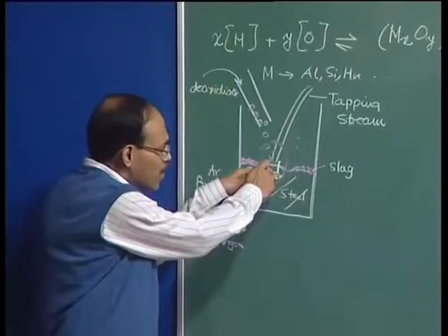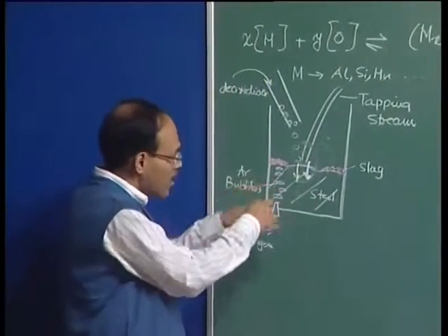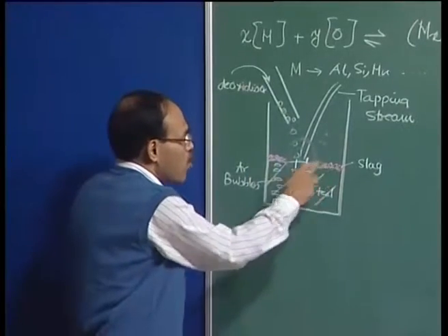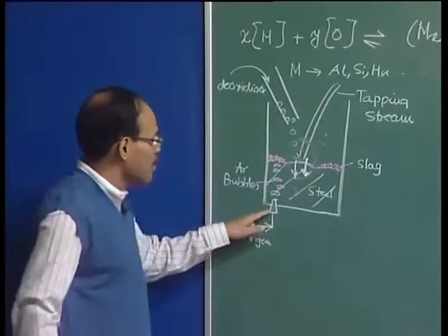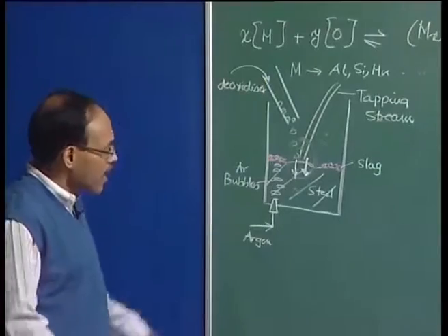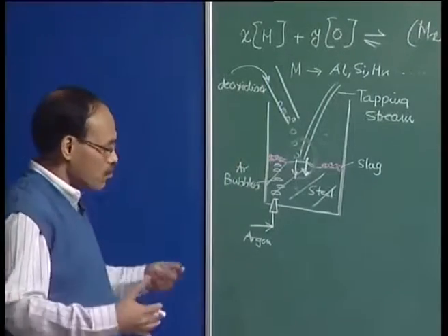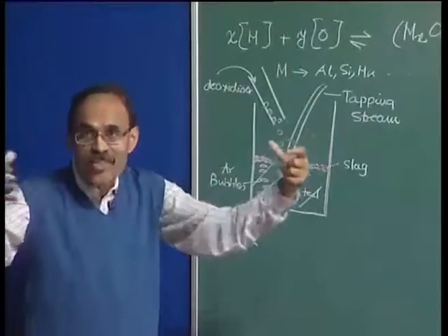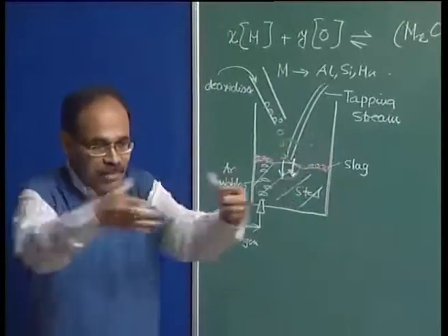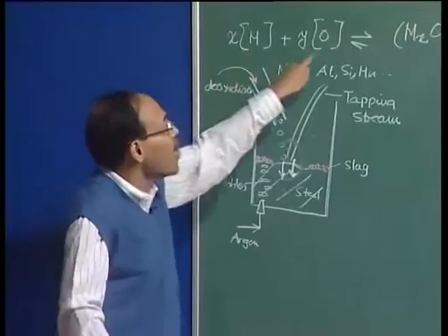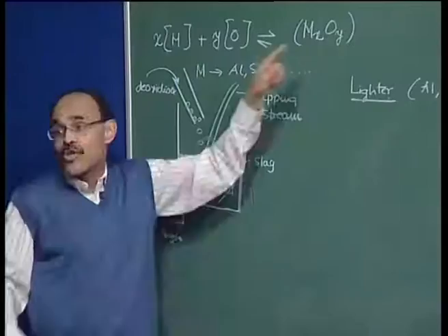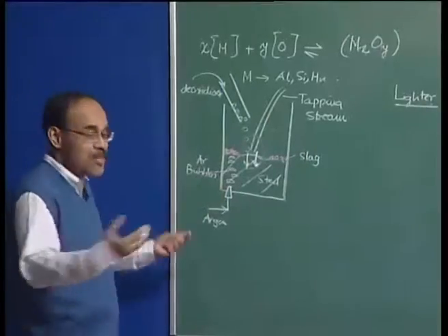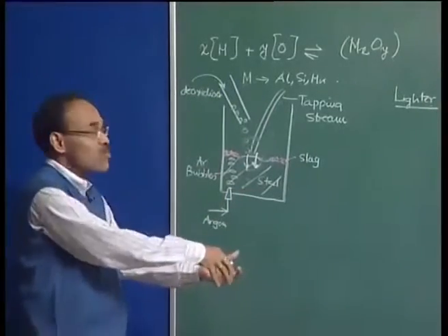As the deoxidizer elements get inside the bath, they melt and dissolve, react with oxygen, slags form, and I have shown with colored chalk here that the formation of the slags, simultaneously the stirring goes on, because in the mass transfer reactions, we always want that the oxygen and metal must come in contact with each other, and then only this product is going to form. So, we want to create a kinetically favorable condition. We want to create some stirring all the time, such that oxide is transported from one place to another place.